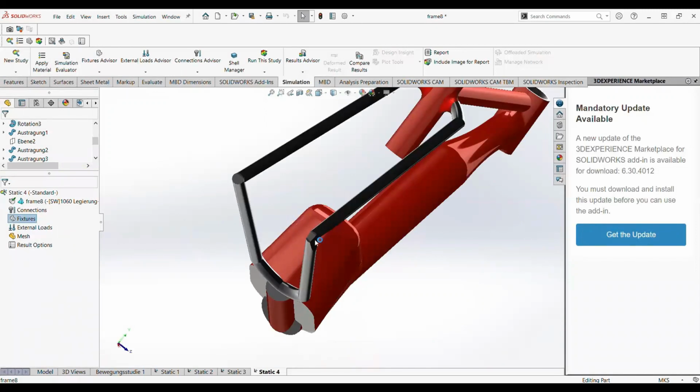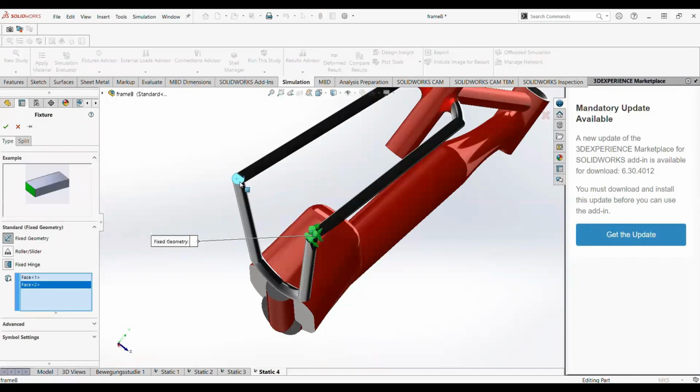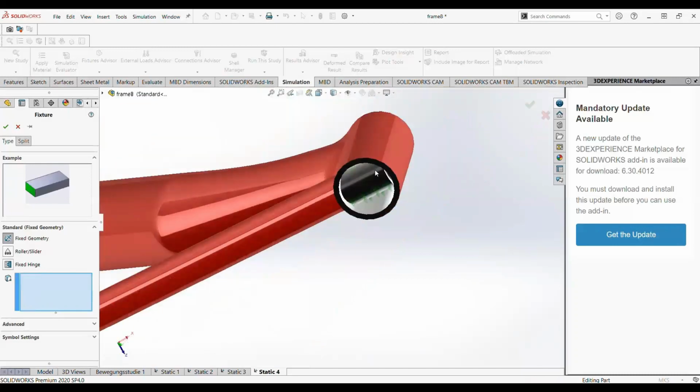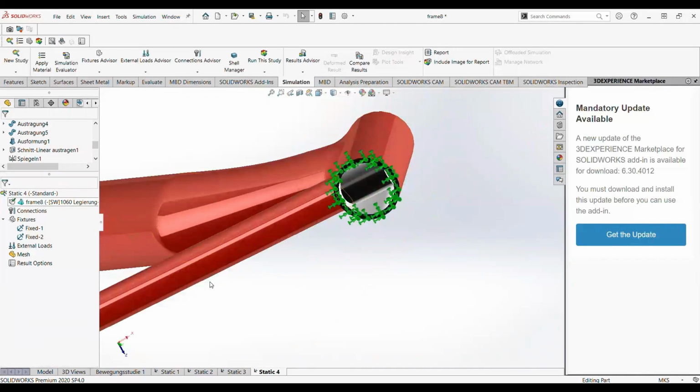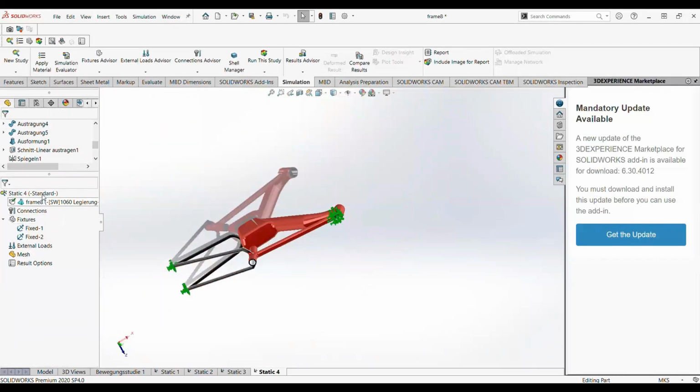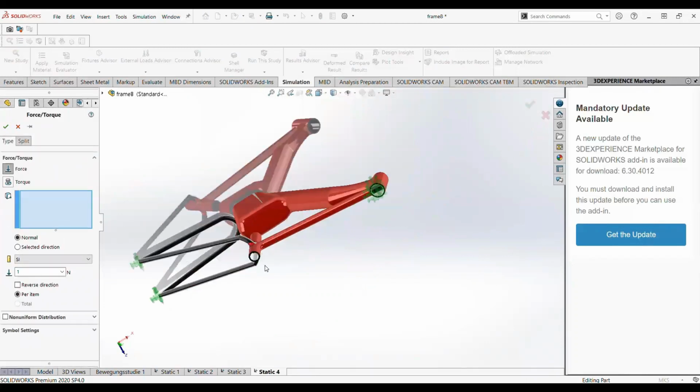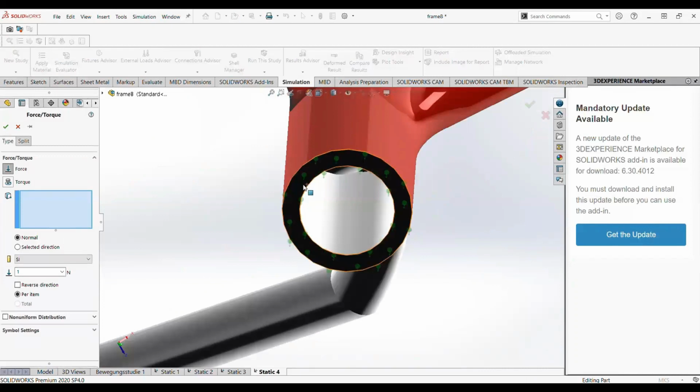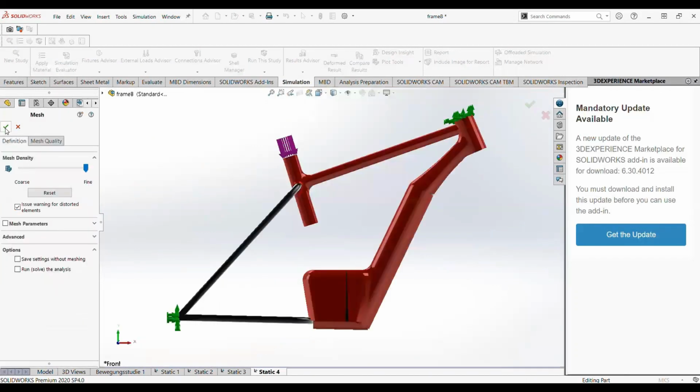Let's say the computer does not understand where you will put the load and which part is static and which part will be dynamic or move through the load. So you have to tell the computer that this part and this part will be fixed, and the other part you're supposed to put the load on. So these are the settings actually. I made it like this because I do not need to describe something when you have the problem. So immediately you can see and simulate.